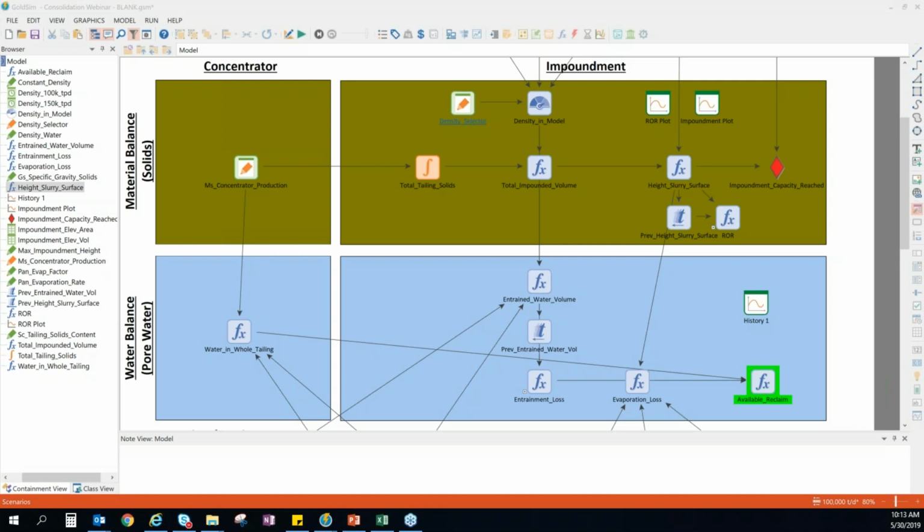And then next question, just to confirm, this method accounts for release of water from densified tailings in the lower layers due to consolidation from weight of new tailing. Yes, that's a very good point, and something that I neglected to say earlier. The reason that we even see consolidation is because tailing that's deposited early on is loaded up as new tailing is deposited on top of it. So that new tailing loads up the old tailing, and that load is what drives consolidation of the lower tailing layers. All right, so every new layer of deposited tailing results in additional consolidation of the tailing below it.